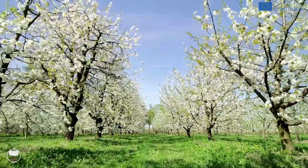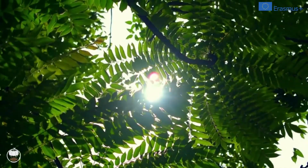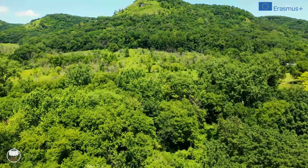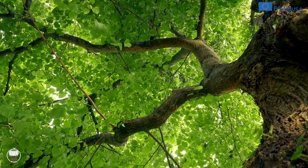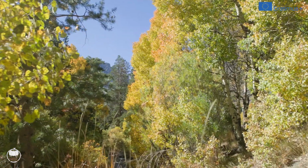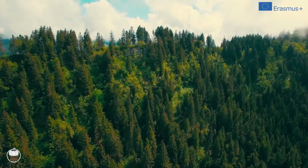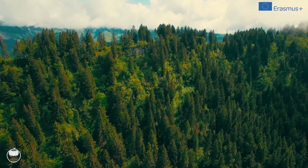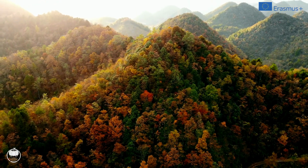These woods are made up of thick-walled cells with small hollow spaces, which makes them heavier than coniferous species. Their woody tissue is more compact and, as a result of that, they offer higher resistance than that of coniferous woods. The terms softwood and hardwood are used as synonymous for coniferous wood and non-coniferous woods.